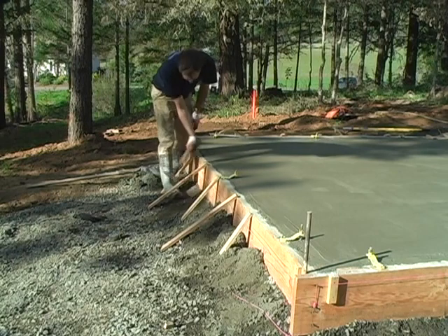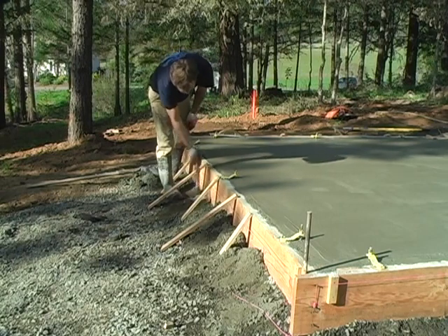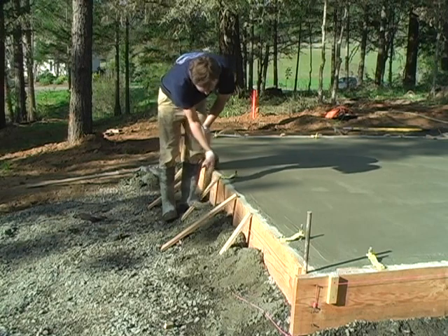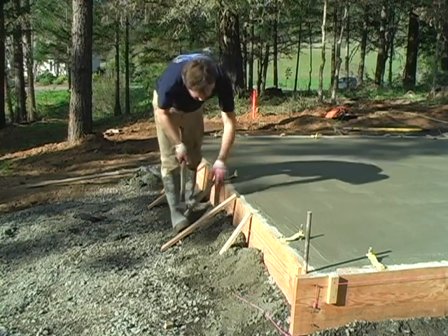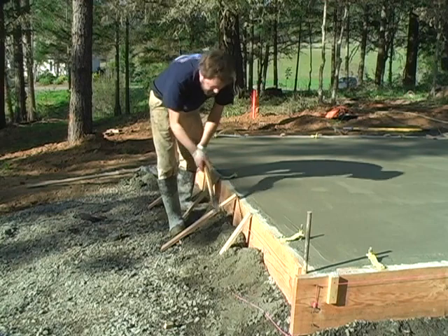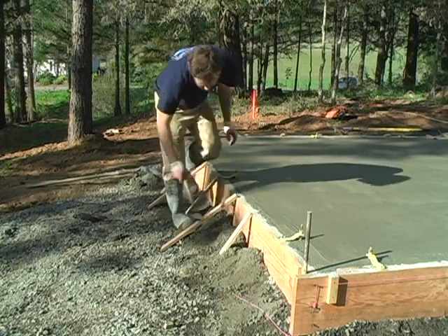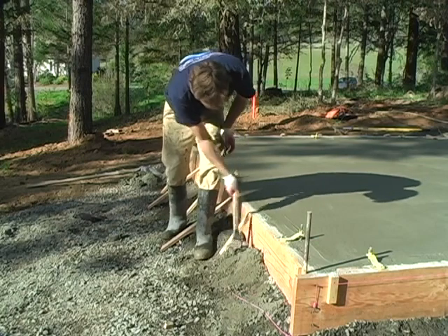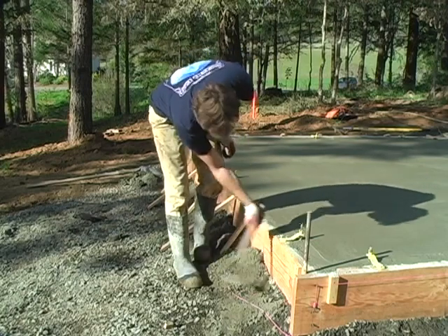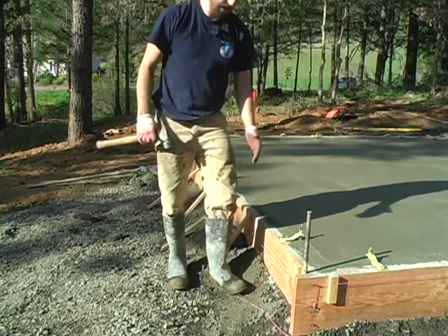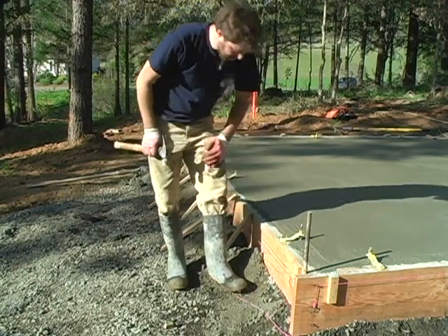Now I'm just going down the sides, basically vibrating the concrete down so I don't get a honeycomb look, which is, basically if you flatten that down, you can see the gravels and some cavities where the gravel was, and voids and bumps, and it's just an ugly finish. So here, by just vibrating it out like this, the concrete will settle down and smooth out enough to where we get a nice clean finish when we remove the form boards.